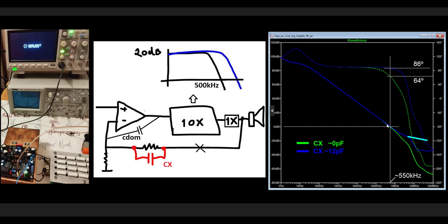Okay, we don't have any impact on the low frequency gain. If we want to go up or down in this gain, this is another important point, we need to touch this dominant pole. If we increase this dominant pole, this line will pass the 0 dB earlier.